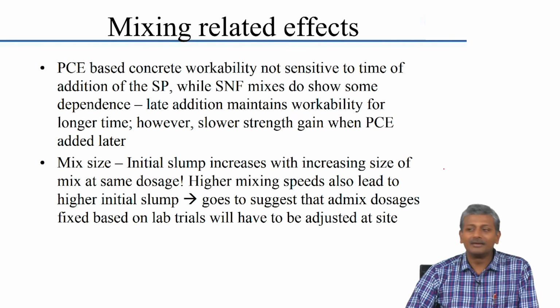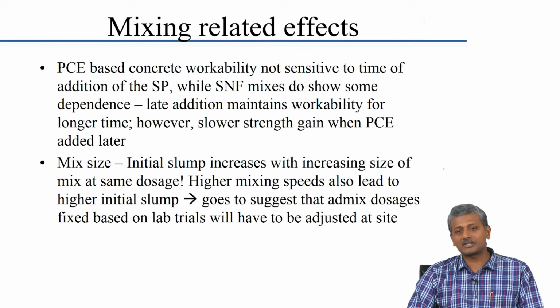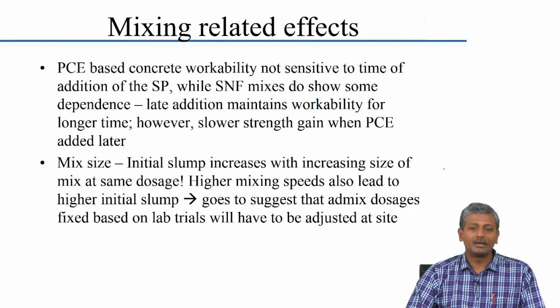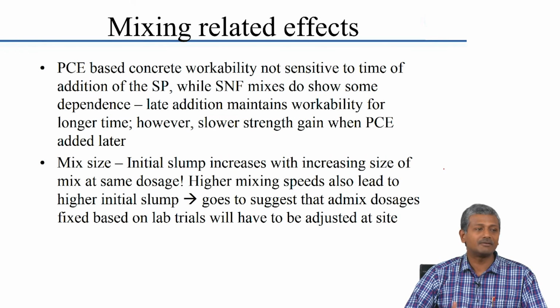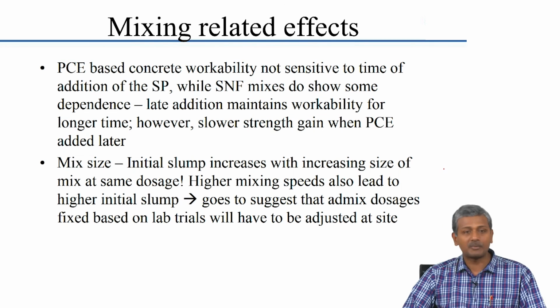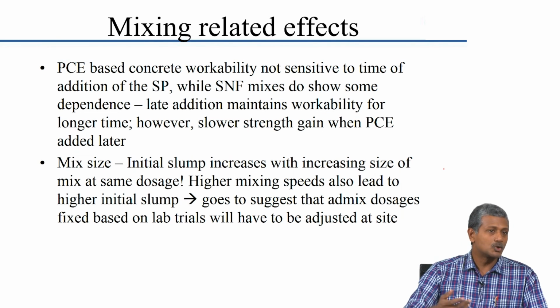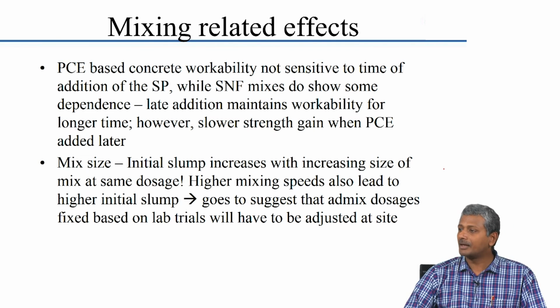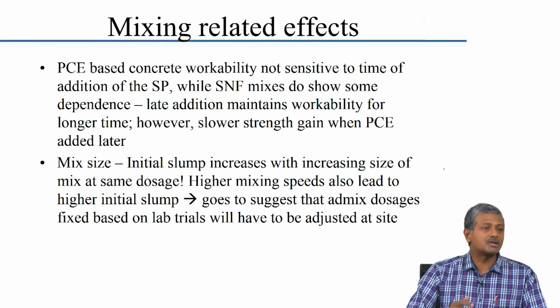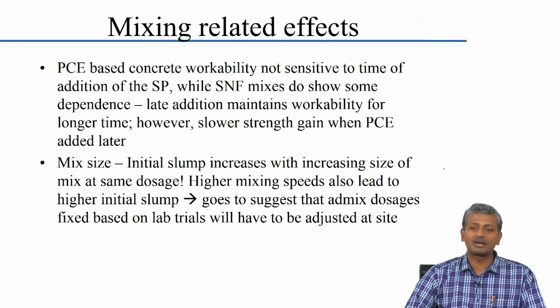I am just explaining the aspects that we were able to correctly conclude and bring to light in a good workshop that we conducted with the Indian Concrete Institute, where we disseminated all this information. And because of this, there has been some development in the construction sites where cement companies and admixture providers have started looking at this usage of marsh cone and mini slump tests, and now it is almost become a routine practice to actually adopt this for large scale projects where you can really have major repercussions if the mix does not have a compatible combination.